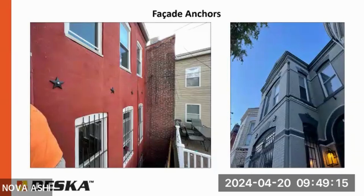So something that can also happen from those steel lintels expanding is they apply a very powerful force upward on the facade, or in this case, these are full masonry brick walls. And if the wall is too heavy, or let's say there's 3 or 4 stories above it, the lintel is not able to lift that. So what ends up happening is the wall buckles outward, has nowhere else to go.